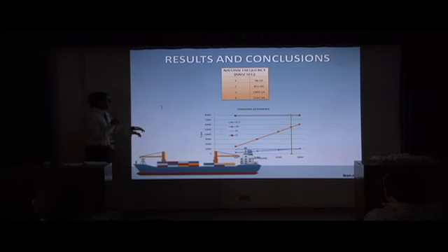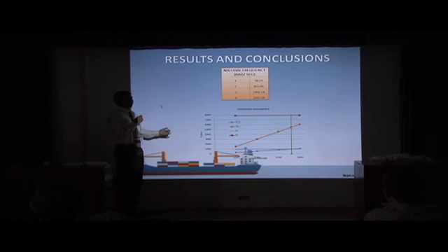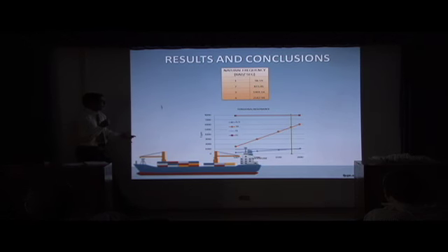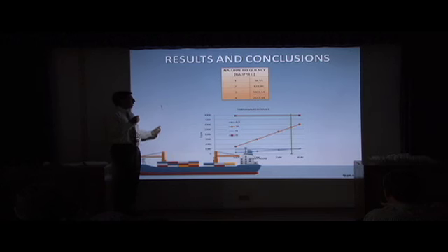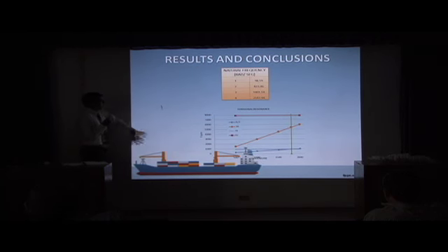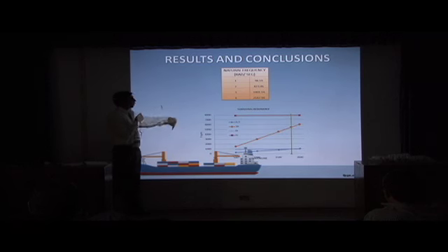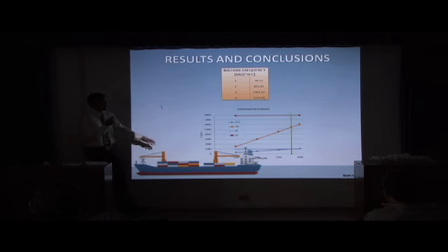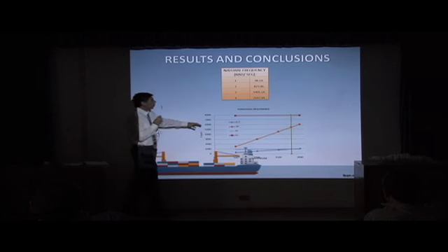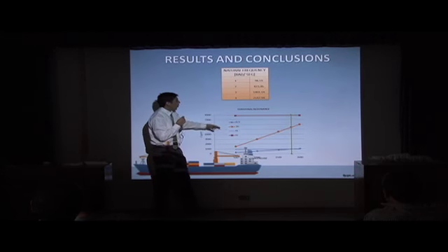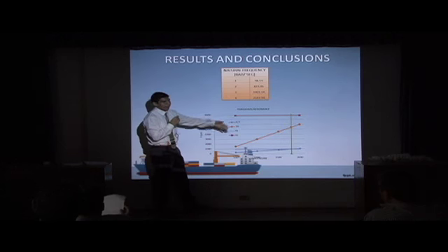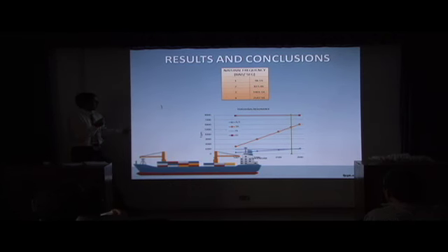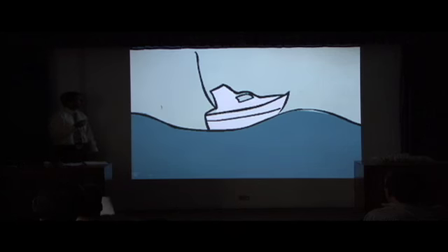In conclusion, we have the model of the engine, gear and clutch, and the propeller shaft, to calculate the natural frequency. We say that this system doesn't have a problem with vibration, because the natural frequency doesn't intersect with the major critical of the engine. This is all. Thanks.